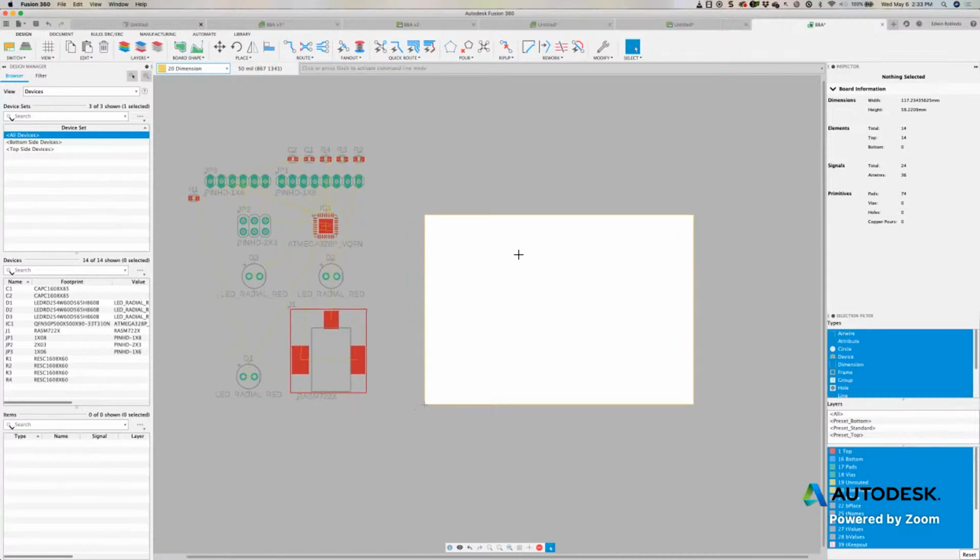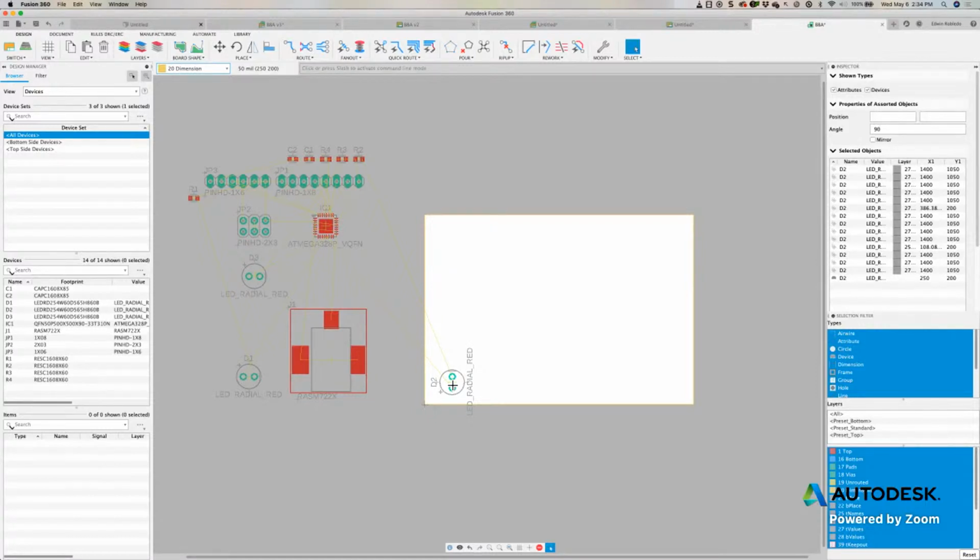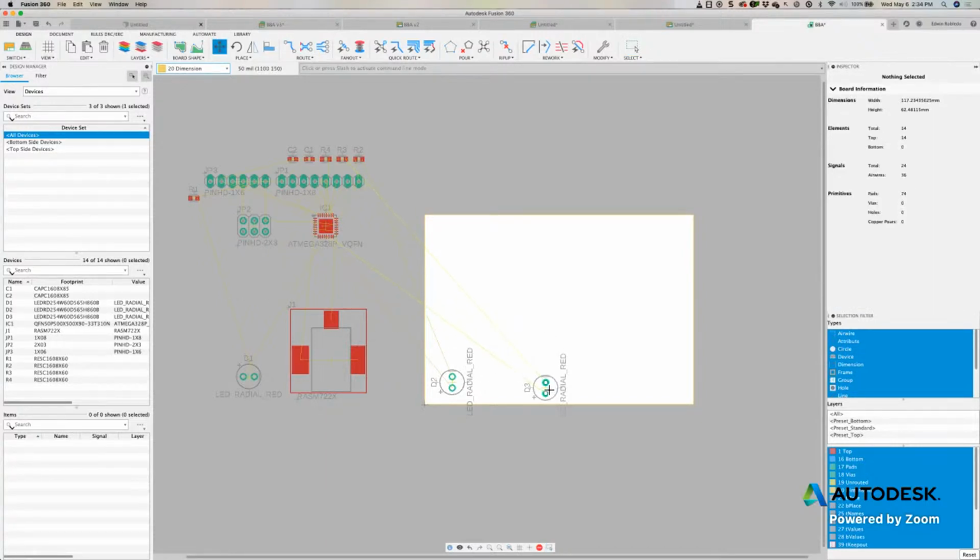Okay, so let's go ahead and start moving our parts. You start dragging them here. I left click and drag to select the parts, and I right click to increment the angle in increments of 90 degrees. Now, you can use the move command and move components in virtually any angle as well. It's just a convenience. It's very common to place parts only at 90 degrees. Now, can you use 45s? Actually, it's very common. I've seen many boards, especially for microprocessors, with parts at 45.